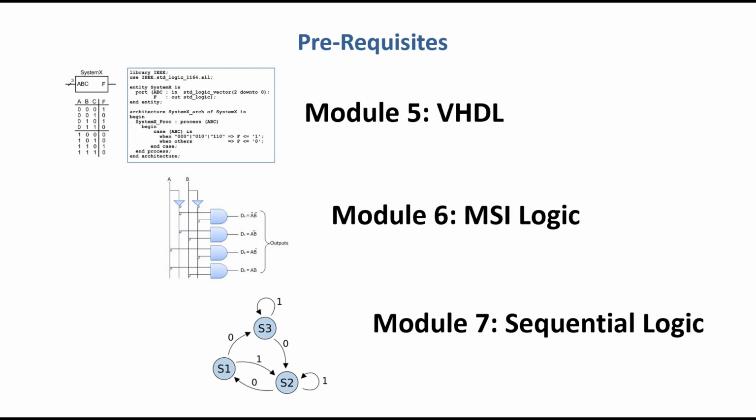This is where we started looking at circuits that could create their outputs based upon both the current value of the inputs and also the past values. So whenever you're talking about past values of something, you're implying that you need storage. So sequential logic is circuitry that has some sort of storage mechanism. Storage is not, in this context, memory arrays, so things like DRAM in your computer. What we used was a D flip-flop. A D flip-flop was a very fast storage device that could store 1 bit at a time, and it would only grab the input and store it upon a triggering event. And the triggering event that we used was the rising edge of a clock.